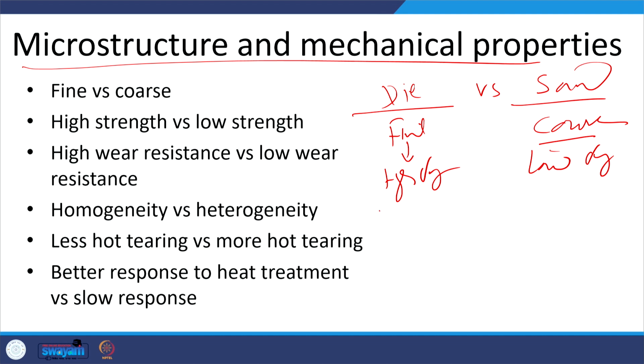The higher hardness of the die cast surfaces, due to the fine grained structure caused by the higher cooling rate, causes greater adhesive wear resistance. On the other hand, the lower hardness of the sand mold casting, due to the coarser grain structure, promotes lesser adhesive wear resistance. So, adhesive wear resistance is completely different in the two cases.